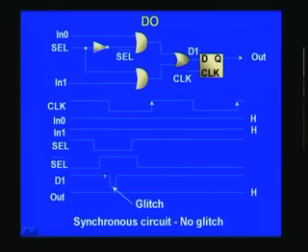So all through it will be 1 except for a small interval here. At this portion it is 0 here, and it is also 0 here. So this 0 will produce 0 here right at the D1, and that is how you get a glitch here, and this is contributed by this inverter as such. It is the propagation delay of the inverter which is responsible for creating this.